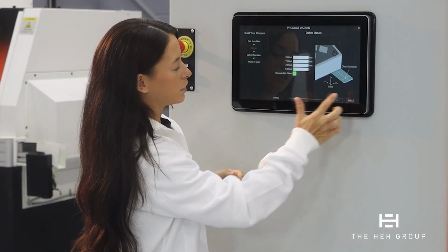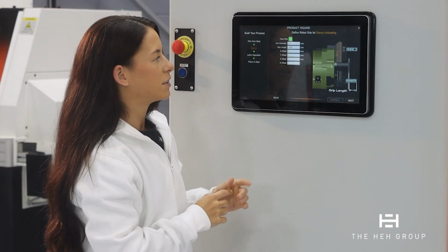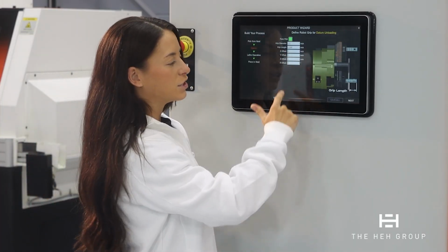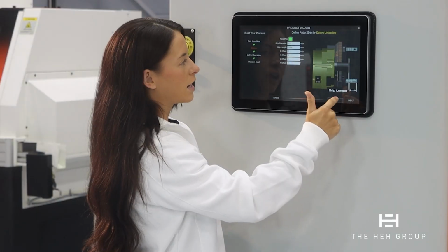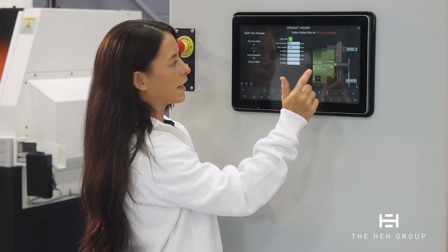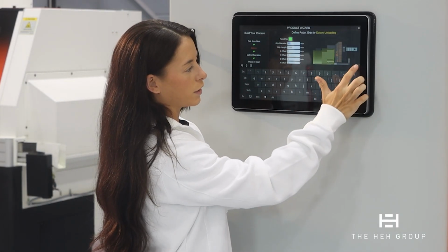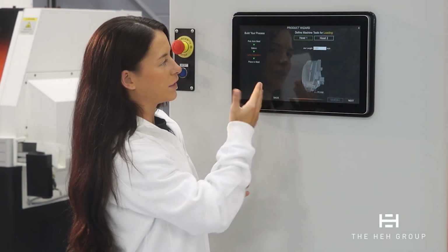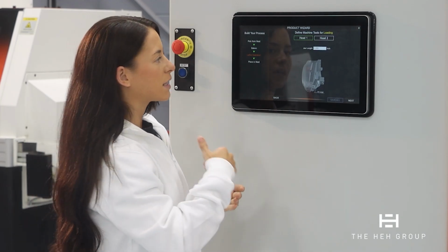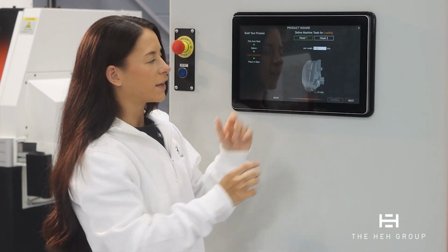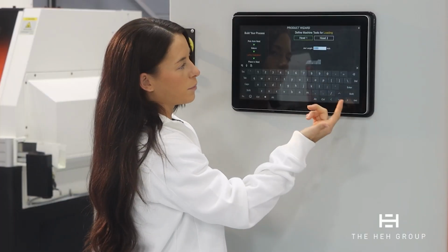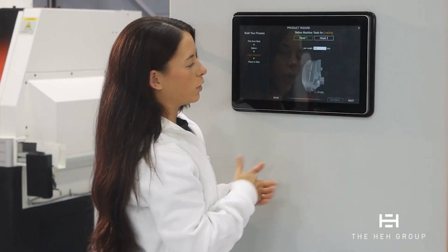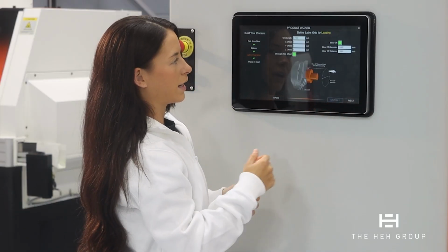So as we continue to move through here, now we're going to do the datum unloading part. Again, you just pick through these, read the diagram so you know what you're looking at. These are all editable, and then you just keep moving through the program. This is for when you're loading the machine into head 1, you want the jaw length, again, editable. Right here we have a 1.55 in there, but let's say I wanted to change it to 1.6. Cool, already changed, and we're just going to hit next.